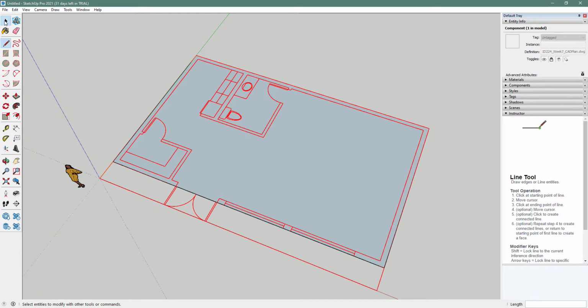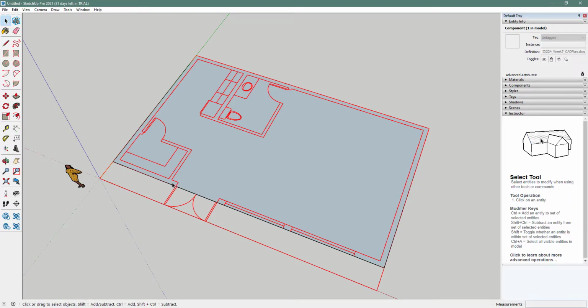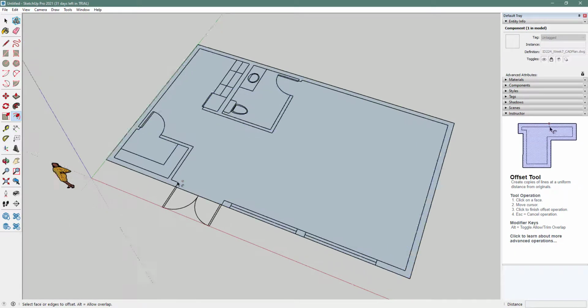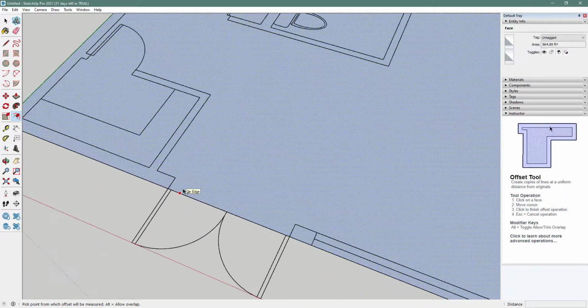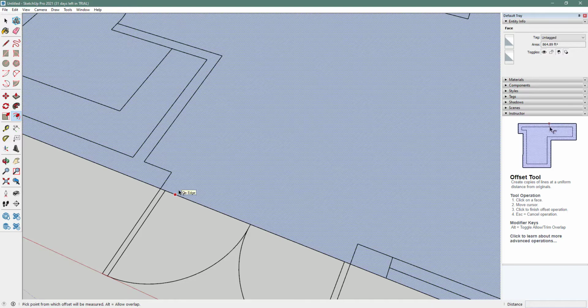The next step is to make our exterior walls have a thickness and also raise them up from the floor. So to give them a thickness, I'm going to use the offset command, very similar to how we work in AutoCAD. Offset. I'm going to come here to this doorway. I'm going to get a little closer so that you can see this well.